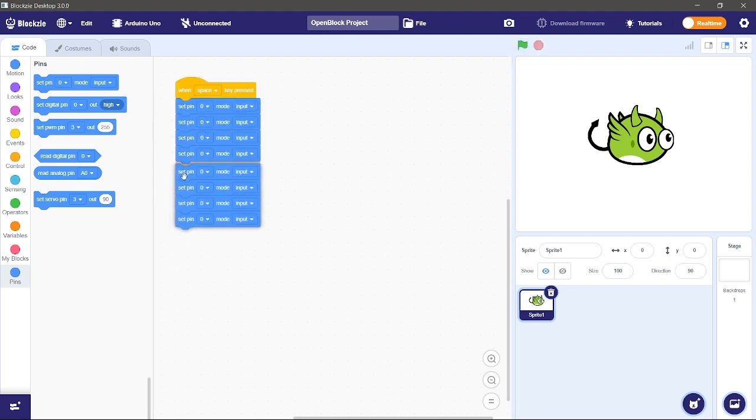8 for that dot. First we have connected the 7 segment with Arduino, and from the circuit section we know that pin number 2 to pin number 9 are used for the 7 segment display. We have used digital pin number 2 to digital pin number 9.